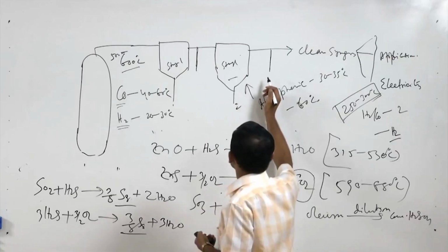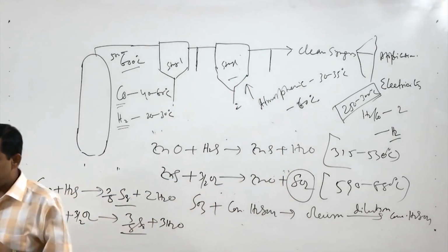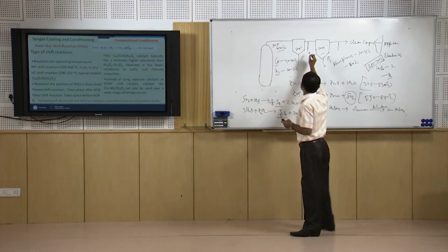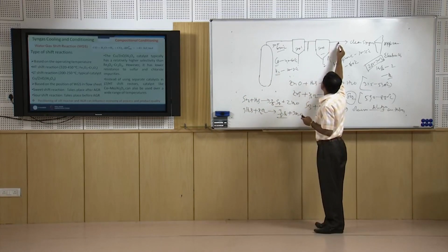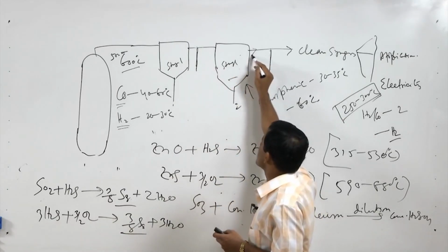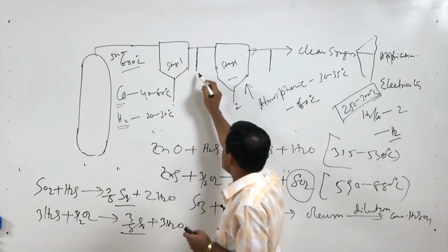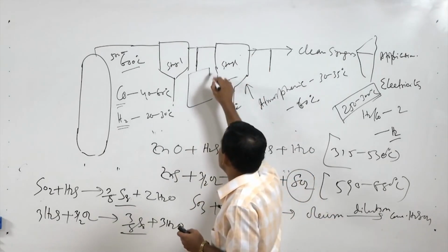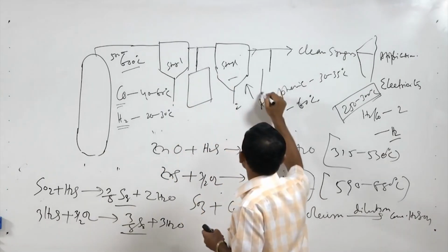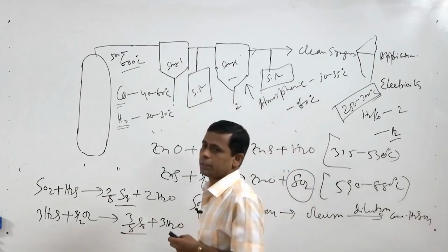If we place it in different positions, then we will have different phenomena. Particularly here the temperature is higher, and there the temperature is lower, because the syngas after cleaning will be at a lower temperature, but these shift reactors require a certain temperature.